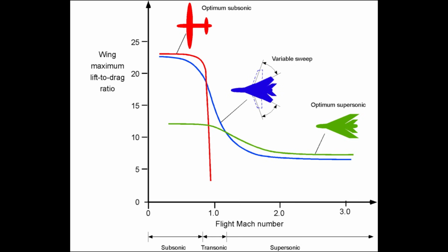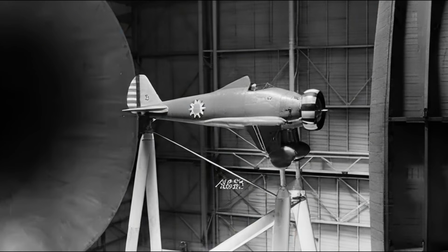These trade-offs were real, but they were manageable through engineering solutions such as high-lift devices, leading-edge slats, and improved flight controls. The key distinction was this: swept wings made high-speed flight achievable, and low-speed problems could be engineered around. The reverse was not true. No amount of engine power could compensate for uncontrolled transonic drag.